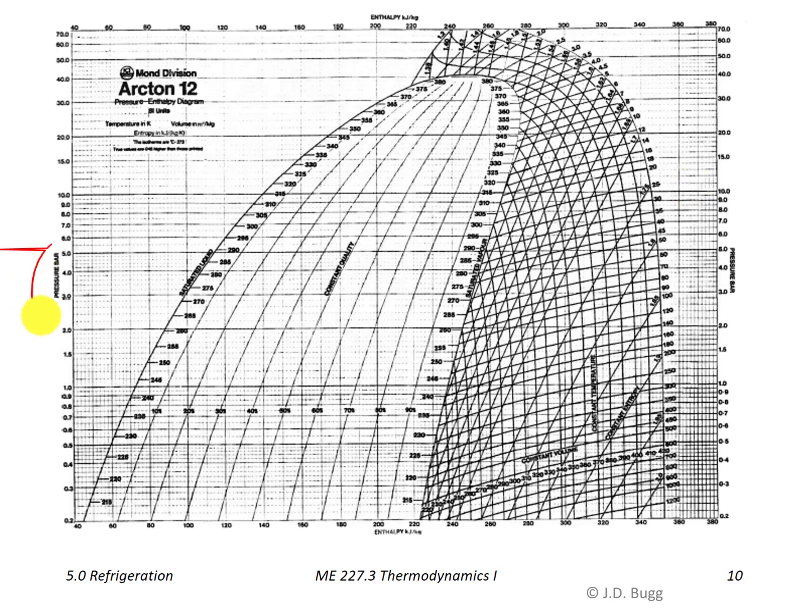And so the vertical axis here is pressure, horizontal axis is enthalpy. We see our saturated liquid line there, critical point at the top, saturated vapor line coming down here. Now, rather than cluttering up this liquid vapor region with a whole bunch of lines of constant temperature going through it, what's typically done is there are just tick marks on the saturated liquid and saturated vapor lines that indicate the temperature, and then we can just connect those with a straight line at whatever temperature we're interested in.